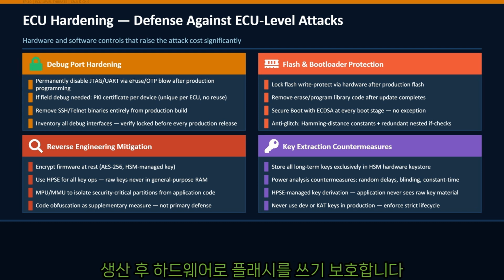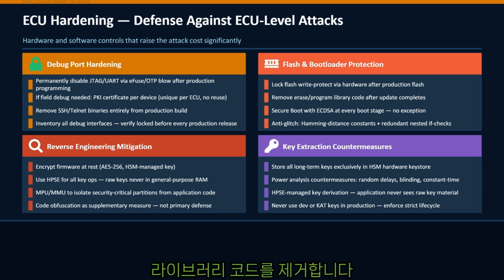Flash and bootloader protection. Hardware write-protect flash after production. Remove erase and program library code after use. Hard removal, not a build flag.